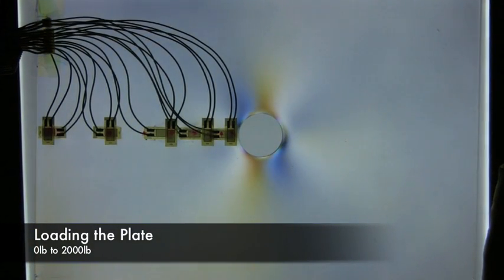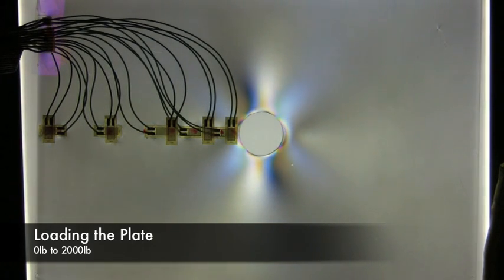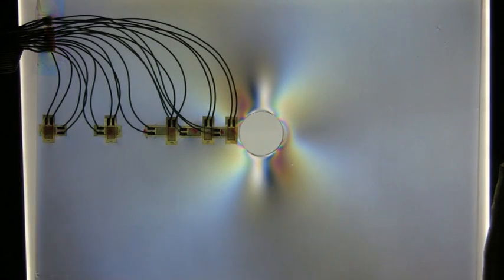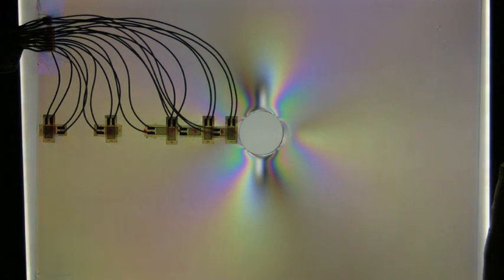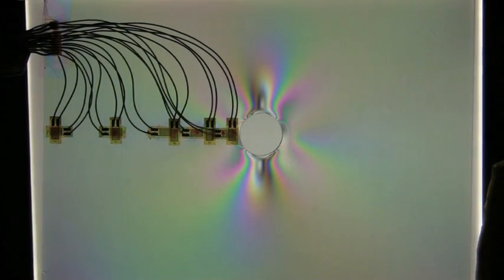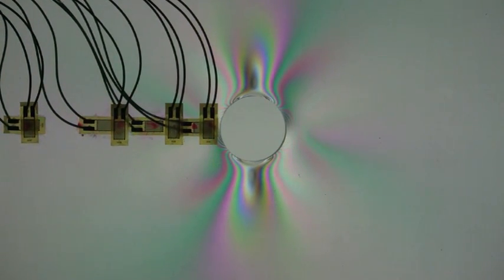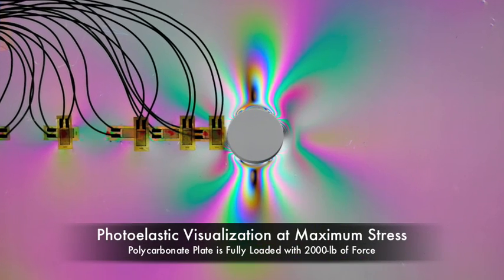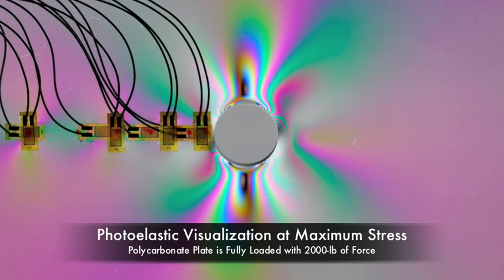Before any load is applied, there are no stress contour lines within the plate. This agrees with our SOLIDWORKS simulation when the model was entirely blue and there was no stress buildup in the plate. As the load increased, the stress concentration slowly accumulated around the hole. Also, you can see that the stress concentrations do not change as drastically further away from the hole as near the hole. This image shows the plate when it is fully loaded with 2,000 pounds of tensile force.